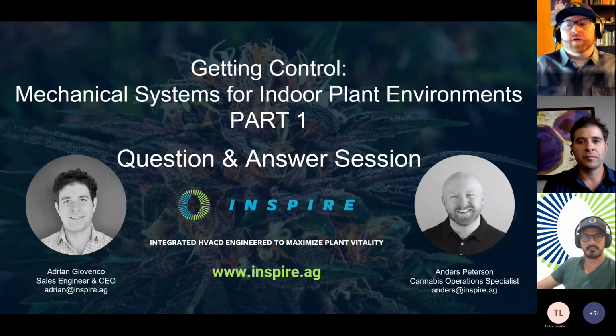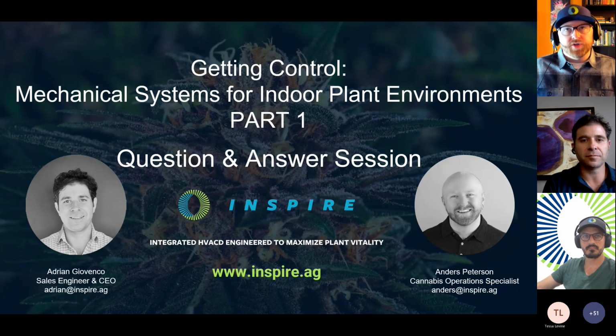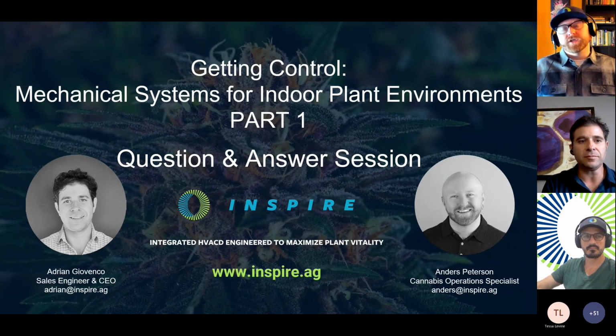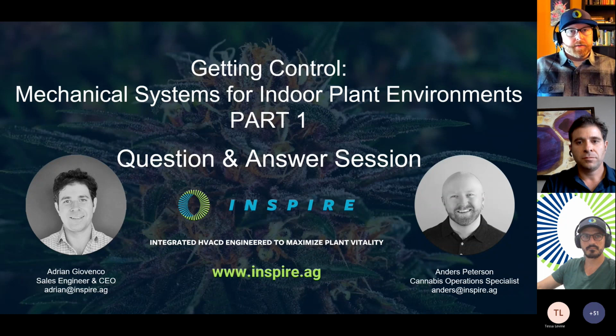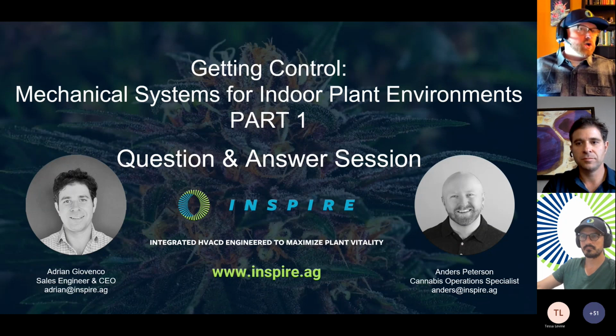One last note there on that question is another good opportunity to service equipment, or good reason to, is if you're operating air-cooled DX equipment in northern climates or very cold climates, with this equipment being outside, like a packaged DX air-cooled system, and you're going to be operating that in low ambient conditions during the winter. It would be a good opportunity to service and make sure that everything is operating up to spec before you enter those cold climate months. Yeah, that's a great point.